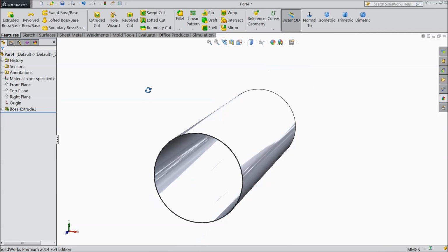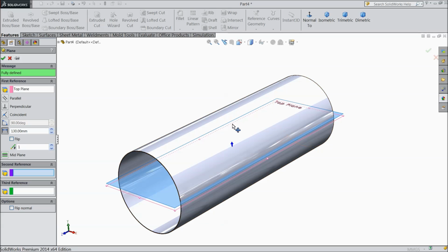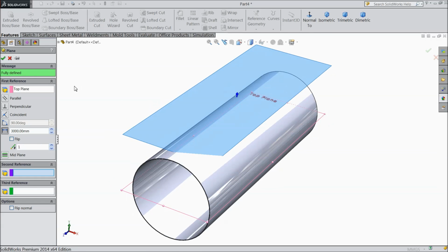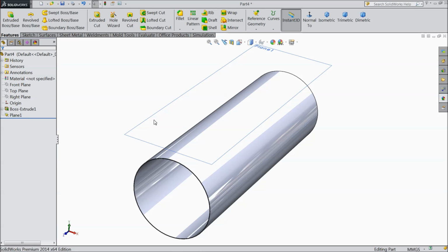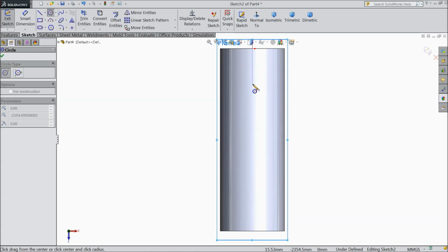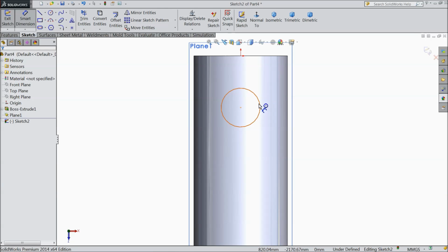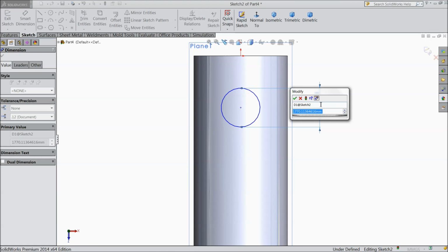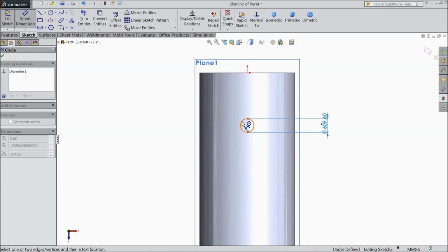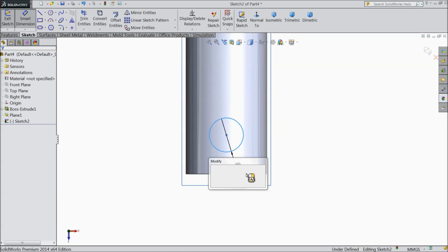Okay, choose perspective, select top plane, choose plane. We want to create a plane here. Select 3000 mm. See, select OK. Now select this plane, sketch normal, and we want to create some hole here. Not exactly a hole, we want to extrude some body. Let's assign the dimension, 609.6 mm, and keep the distance 3000 mm, and this circle also cancel it.